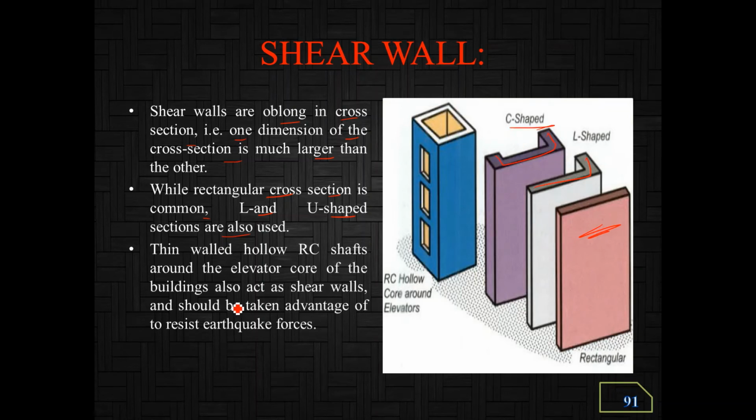Thin-walled hollow RC shafts around the elevator core of the building also act as shear walls and should be taken advantage of to resist earthquake forces. This is the RC hollow core around the elevator.